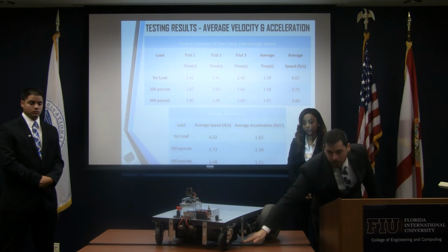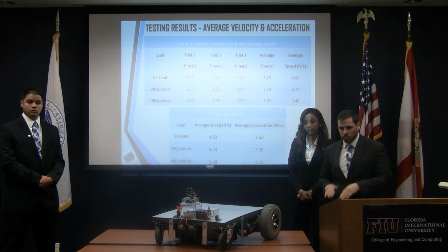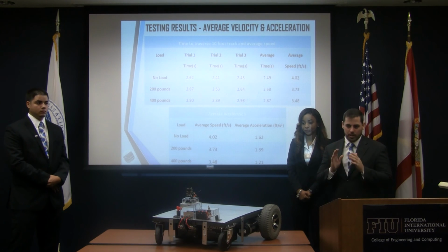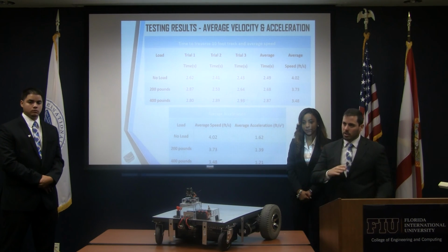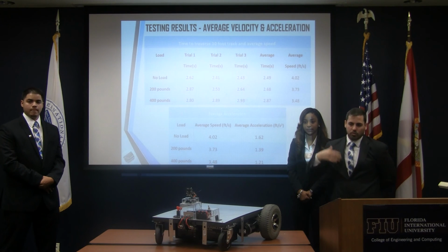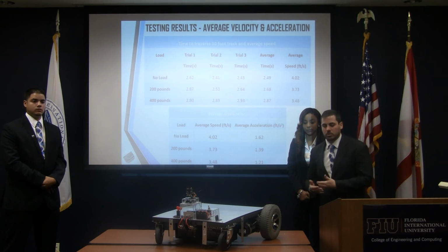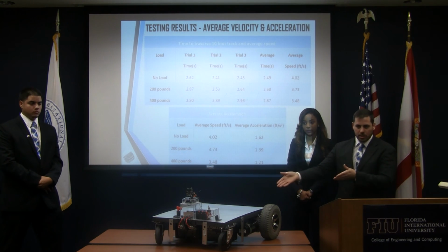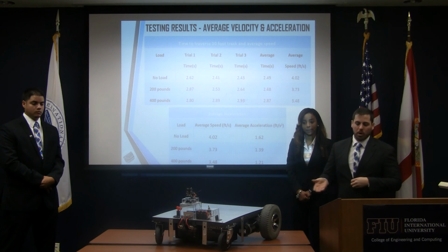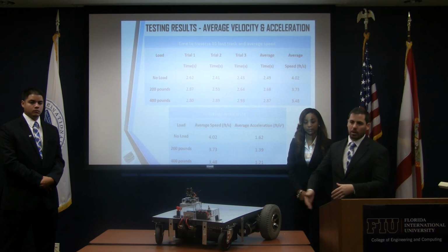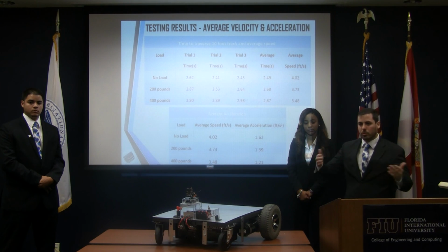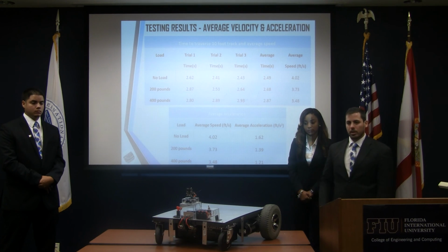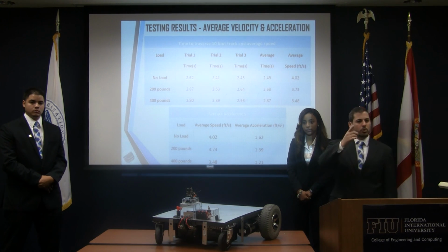As you can see, these batteries are only about an inch and a half off the floor, so it cannot go over anything, basically. It has to be a very flat surface. The environment for this robot has to be very tightly monitored. It has to have good lighting and a very flat surface. So our future work is to go around that and maybe use a different sensor. We don't need these huge batteries to operate this robot, but if we want a longer life, we have to have the big batteries, and it's close to the floor. We can lift it a little higher, but then we have problems with tilting, and if we have a lot of weight, and it's too high, all that has to come into consideration. You had a question back there?